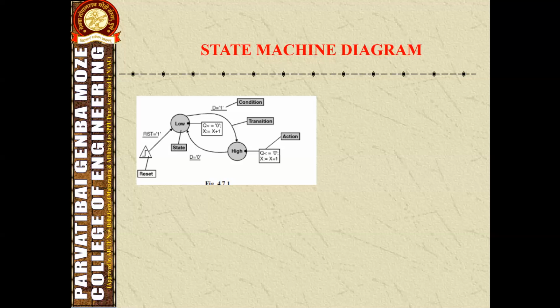Similarly, the transition action. What will happen? It is performed when the machine performs a specific transition from the specific state. The behavior of the signals or ports involved in a transition action differs for combinational and registered types. The assignments to the combinational port signals are executed asynchronously with the changes of inputs to which the transition is sensitive.